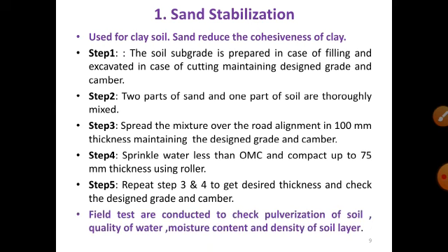Field tests are conducted to check pulverization of soil, quality of water, moisture content and density of soil layer. Pulverization means making particle size fine.